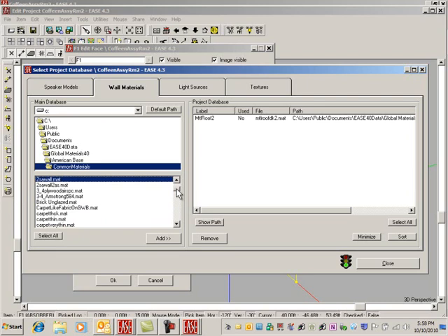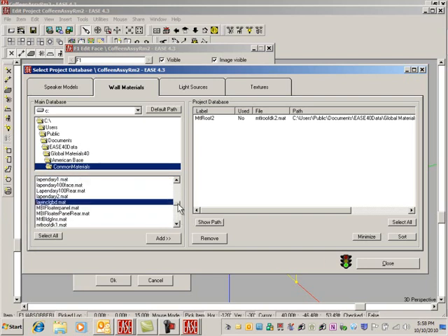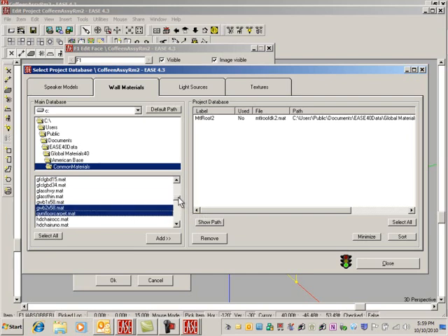Now we can be adding our materials as we build this model. So I'll close this guy. And this wall, well, all the walls really are chipboard. All walls, item 4, 2 layers, 5/8 chipboard, except otherwise noted. So it is chipboard. Good. Start right out, just right, and say OK. And if I maximize this, you can look down here and see gypsum wallboard, 2 layers, 5/8. That's this material right there.